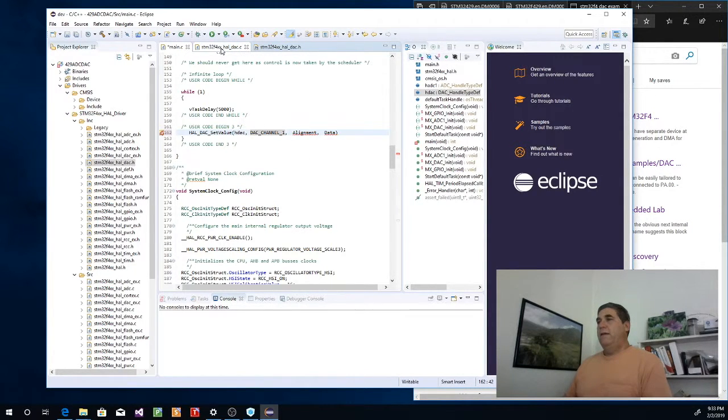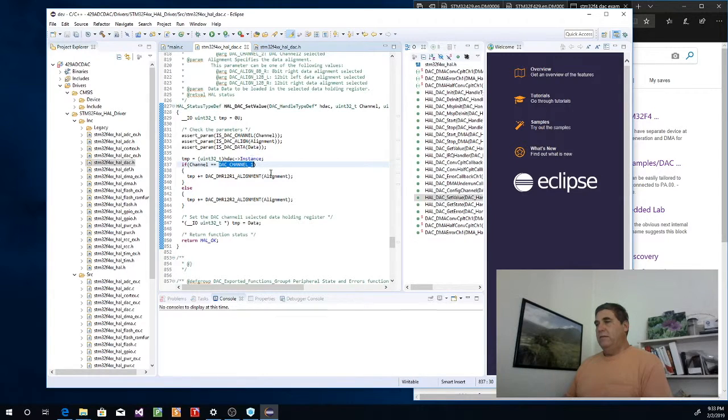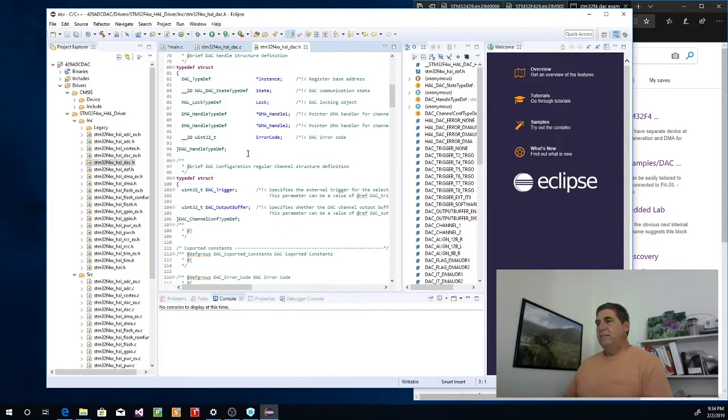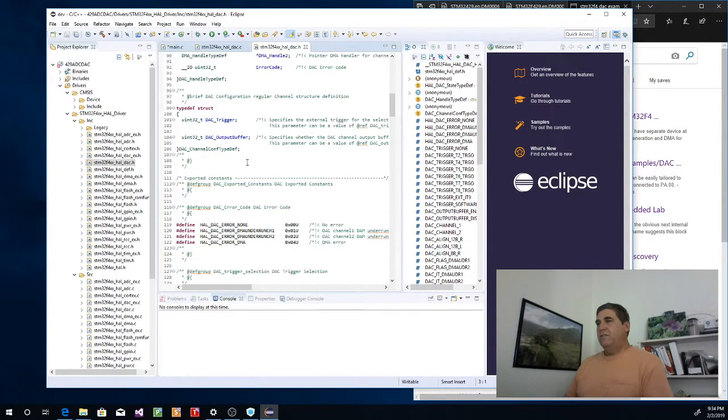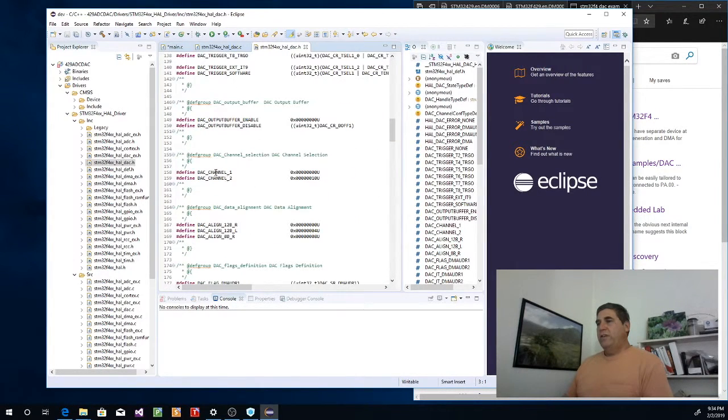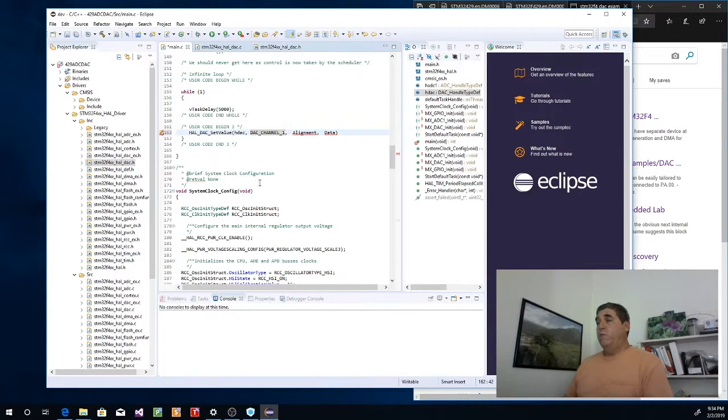Okay, and then we'll look at alignment, which is passed in. Okay, so I think we're going to have to look at the .h to find alignment information. This is the DAC.h. That's the struct for the output configuration. Here's the DAC channel 1. Here's alignment. So I believe that 12-bit right is what we're going to start with. I think that's the correct one. If I'm wrong, we'll find out. Things won't work. So I'm going to set that alignment.